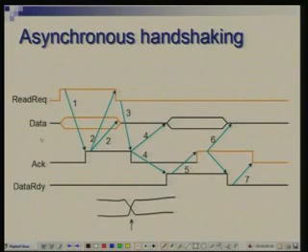But you notice here a third level. This third level indicates that the bus is free, there is nothing on it. These buses are organized as what is called a tri-state bus. There are 3 possible states: 0, 1 and a high impedance state. High impedance state means that everyone connected to the bus is in fact disconnected. It is neither trying to put a 0 nor trying to put a 1. So the bus is in a floating state.